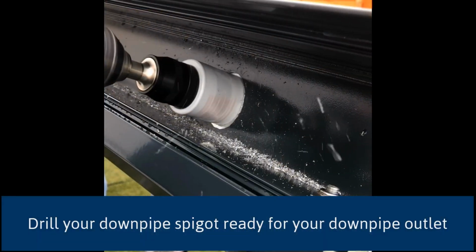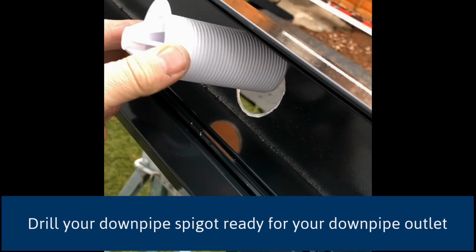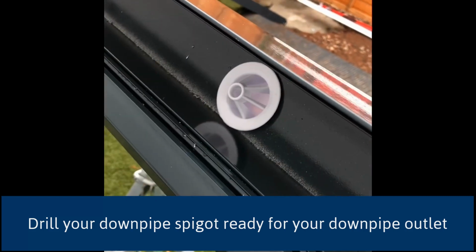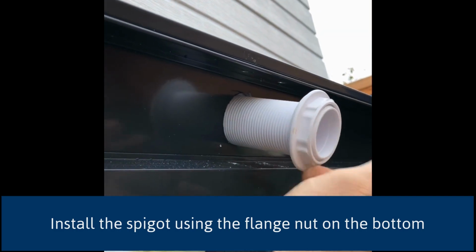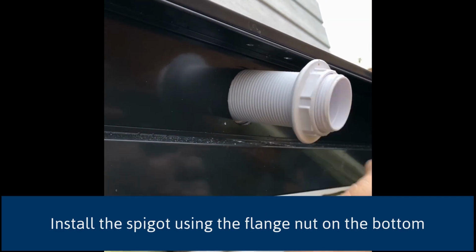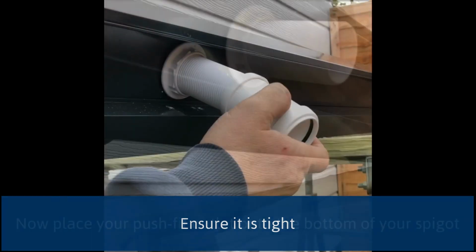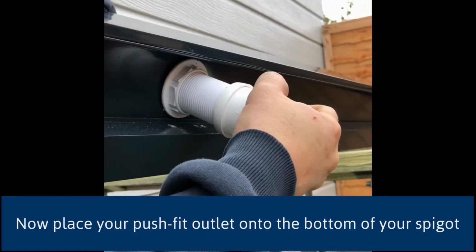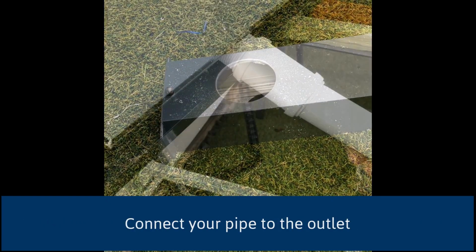Drill your downpipe spigot, ready for your downpipe outlet. Now install the spigot using the flange nut on the bottom. Ensure it is tight. Now place your push-fit outlet onto the bottom of your spigot and connect your pipe to the outlet.